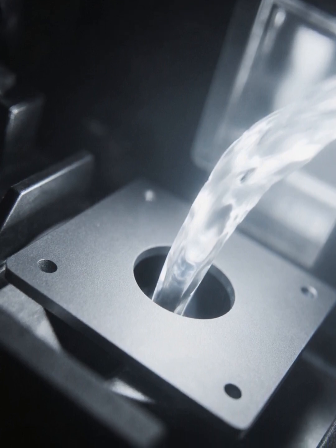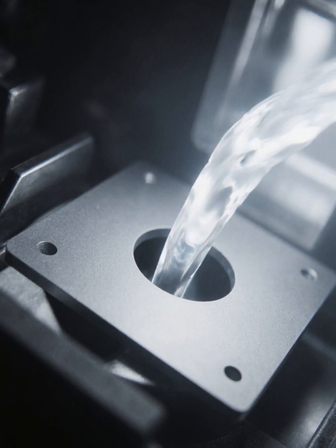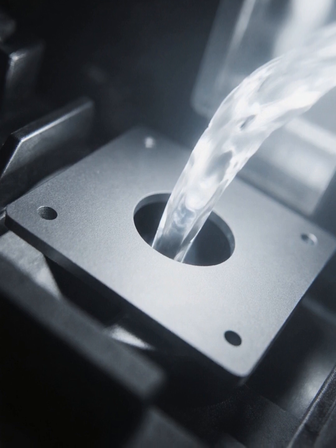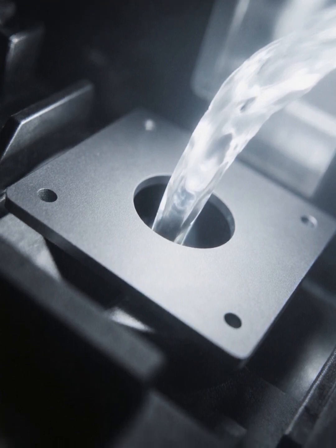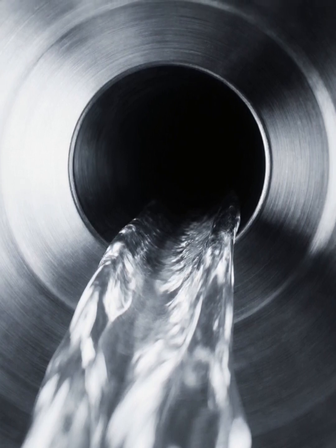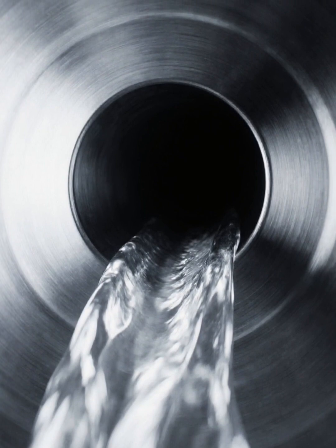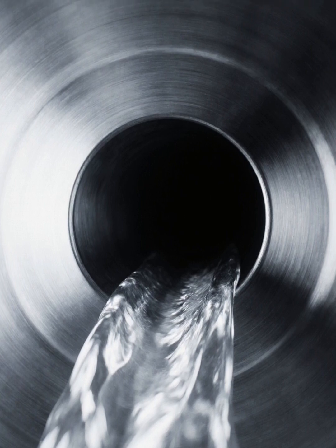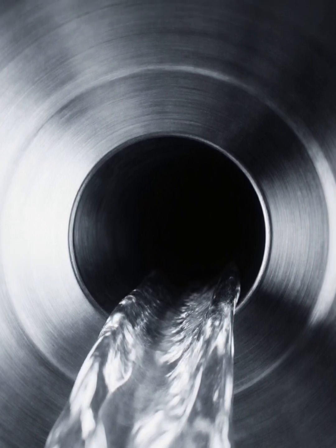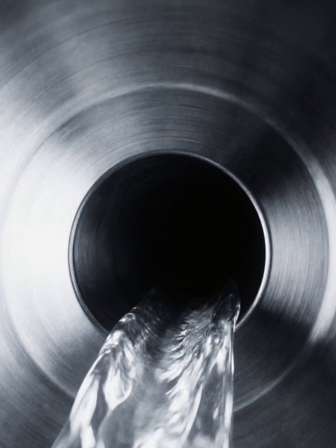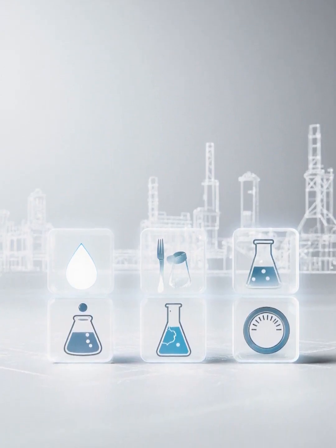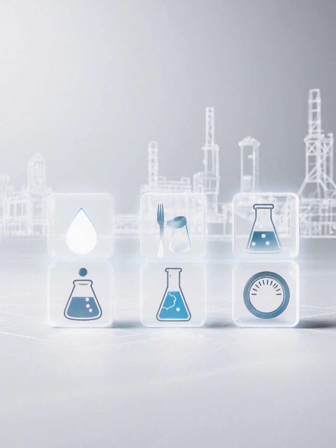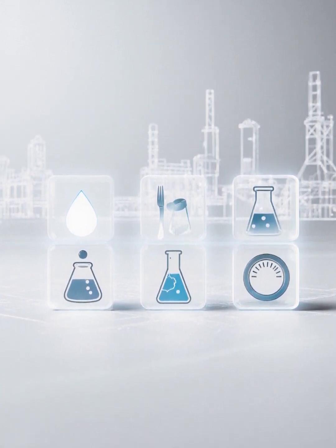Orifice flow meter mechanism. A thin plate with a sharp-edged hole, the orifice, restricts flow, causing a significant pressure drop. Venturi flow meter mechanism. A smooth, gradual narrowing, the throat, followed by a gradual expansion, converting pressure to kinetic energy with minimal loss. Applications: water, wastewater management, oil and gas, chemical processing, HVAC and utilities, food and beverage.